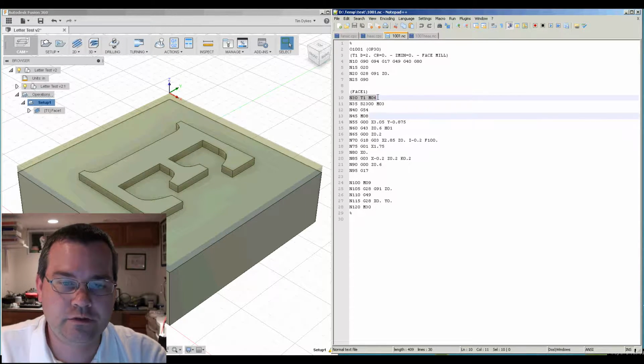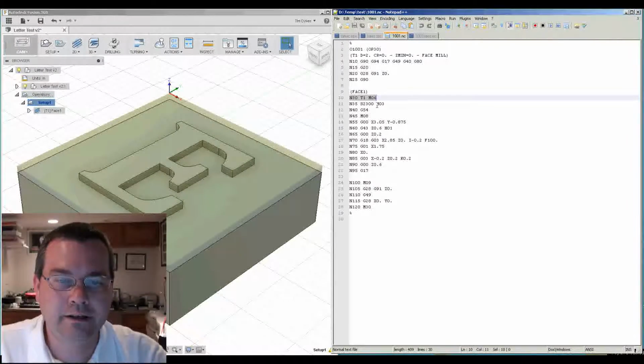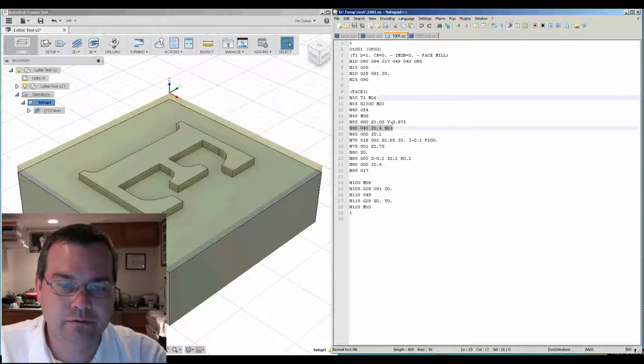If your tool change position is at the top of the machine, this will turn your coolant on when your Z axis is at the very top of the machine, and you're going to hose down your entire machine. It happens on my Fidel. This is a change that I made to my post-processor as well. What we would like to do is have the coolant turn on after the initial Z movement. So here's the first Z movement that applies the tool offset and moves to the clearance plane.